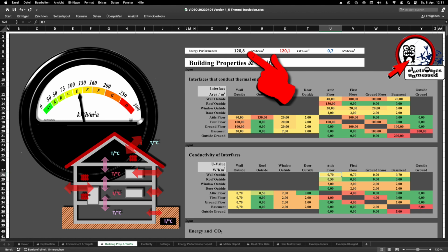If you are now thinking about improvements, then the question is always which measures can be taken to achieve most benefit. What thickness of wall insulation to choose? How much money do you want to invest in well-insulating doors and windows? A simple measure would be the insulation of the roof or the false ceiling to the attic.